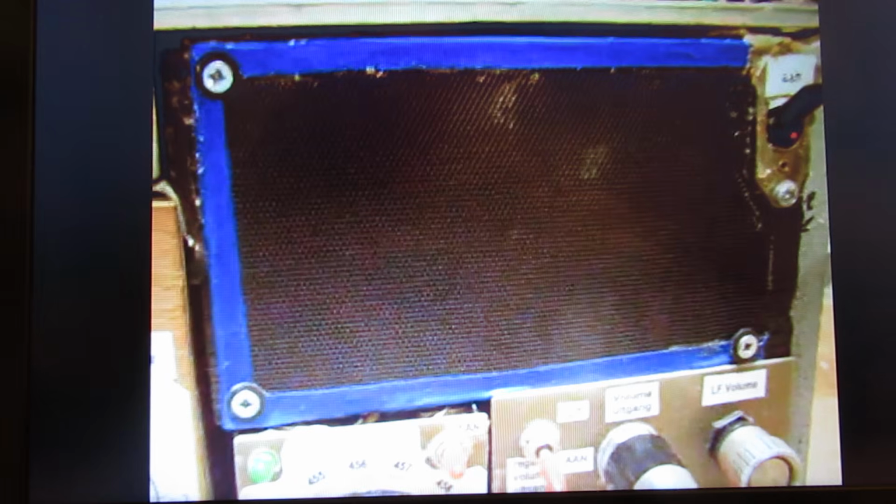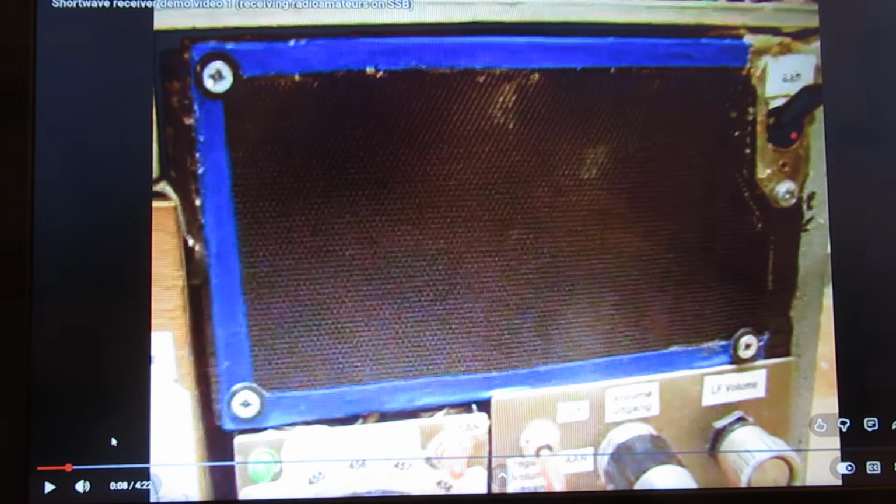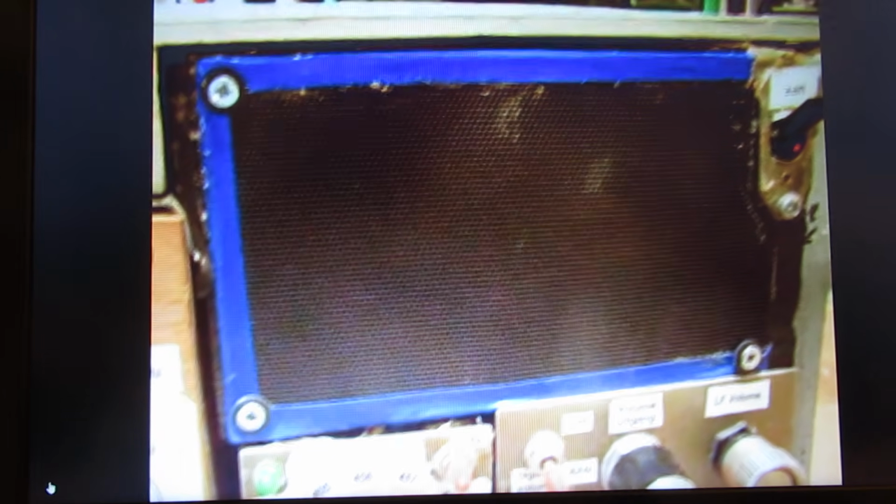So to make a transmission audible and intelligible, you must add the carrier wave, inserted into the intermediate frequency amplifier. And this is an example. It's a very old video that I made in the past, but anyway, it shows how it works. So let's look.